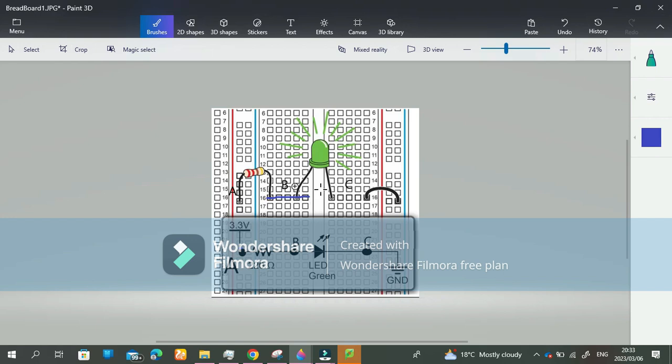Now, I also mentioned that there is a break in the middle of the board where sections 2 and 3 are isolated from each other. Therefore, this allows us to connect our LED across the board, ensuring that current flows through the LED instead of short-circuiting it underneath. And now our wire is going to go from our LED to the node C, which is going to be our series line that is indicated by this blue one here. And this is connected to our ground, or the ground supply, which is connected in series vertically.